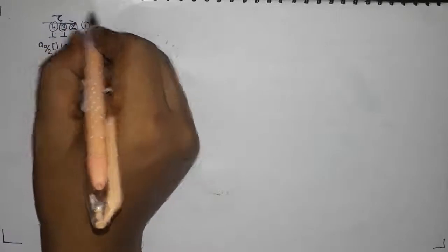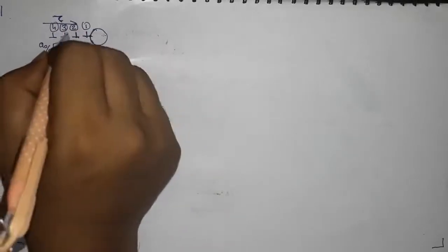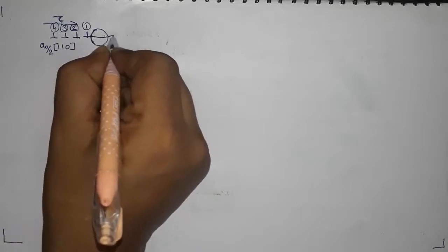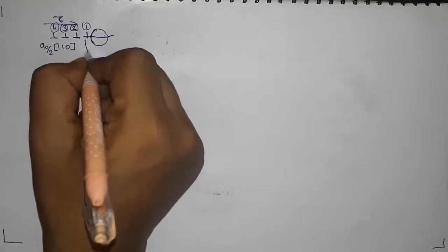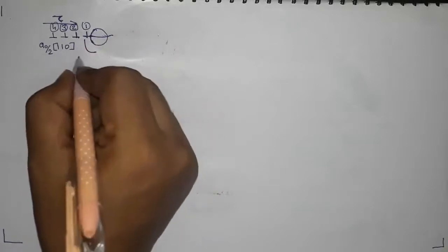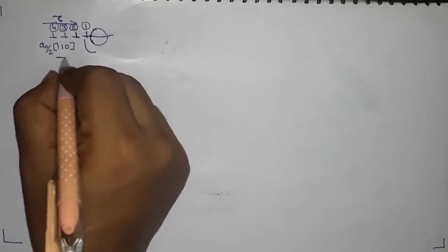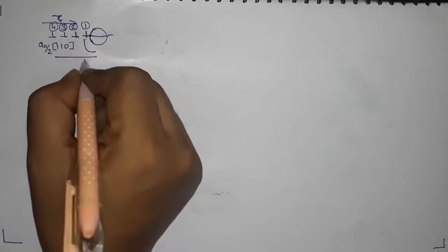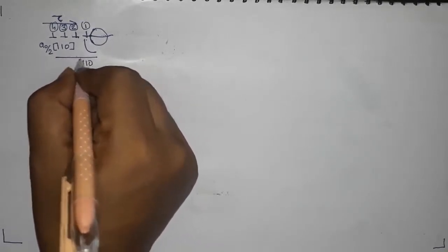I will have to increase the stress. Okay, and then when I increase the stress, it can either cut this precipitate through, or it can cross slip if possible, so it can find another plane which is parallel to this, but the precipitate is not there, and so this is another